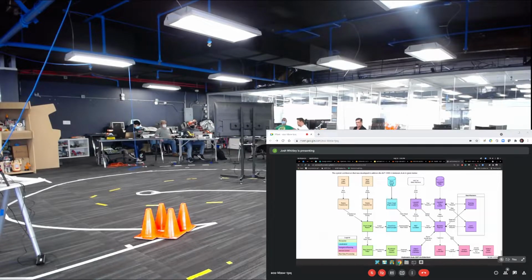From there, that fused point cloud would go into, for perception, a ray ground filter, which would separate the ground points from the non-ground points. Then we would do Euclidean clustering, which would cluster each of those based on distance and movement and so on into groups. And then we would use those detected groups to try and plan around things.